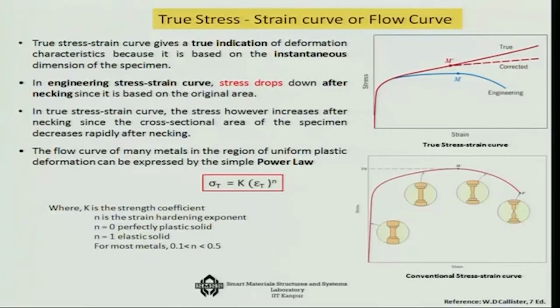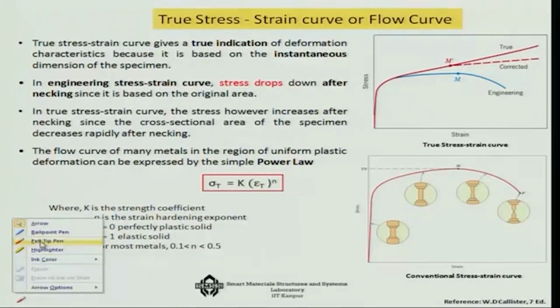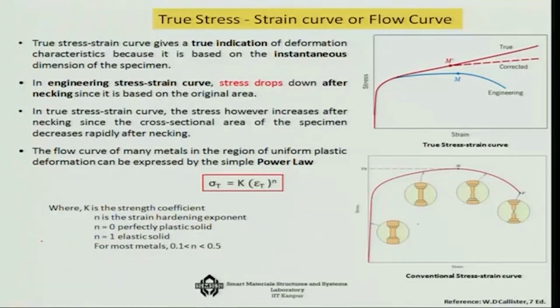If we actually consider, however, the true stress strain curve, that means if we consider that the area is actually changing, as you are deforming, this area is becoming smaller and smaller, the neck formation is happening.